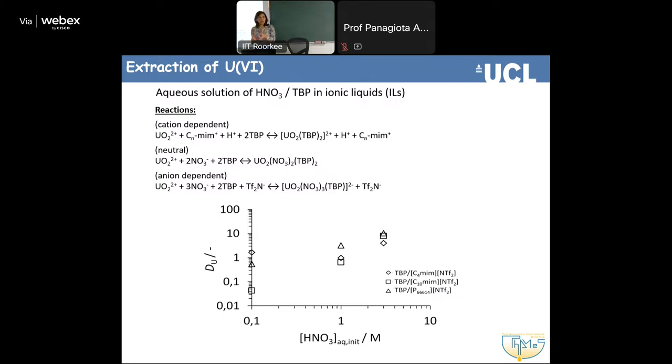You have CO2 in a gas, and you have the amine solutions. And you might put stuff inside the amine solutions to move the equilibrium so that more CO2 leaves the gas to go to the amine solution. So this is what will happen. We get these experiments to get each of these points. We might have to wait 2, 3, 5 hours, because we have to make absolutely sure the system is at equilibrium, that this is all it can get between the phases.